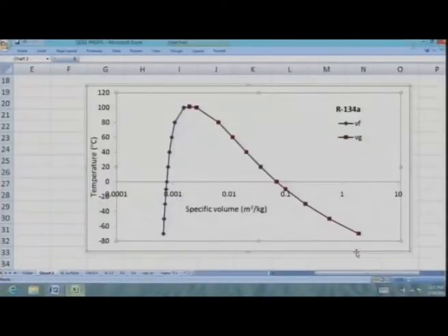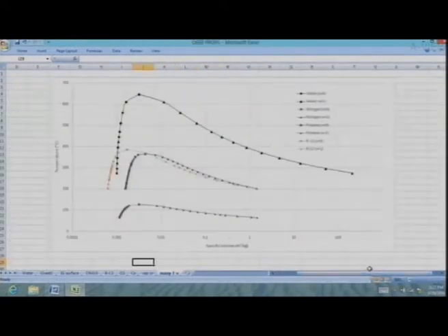And now let's see the same thing for different substances. What I've tried to do here is make a similar TV diagram for different substances. We can do that because temperature scale is absolute. It is the same temperature scale everywhere. And the specific volume is also an absolute scale, so that is meter cube per kg here. Okay, there is a small change here. I've written here temperature in degrees Celsius. This is not right. This is temperature in Kelvin. So we can make that change here.